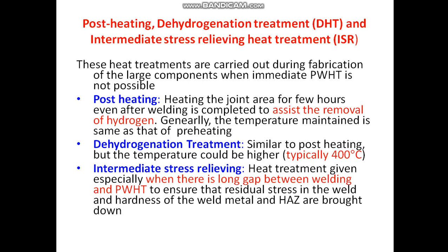When there is a sufficient gap between the welding operation and post-weld heat treatment, the ISR process is highly recommended, to ensure that the residual stresses produced during welding and the hard microstructure in the weld metal and heat affected zone are brought down, and properties become suitable for service application.